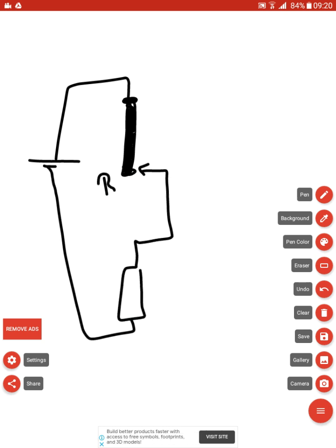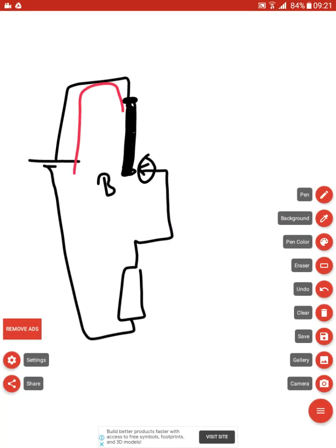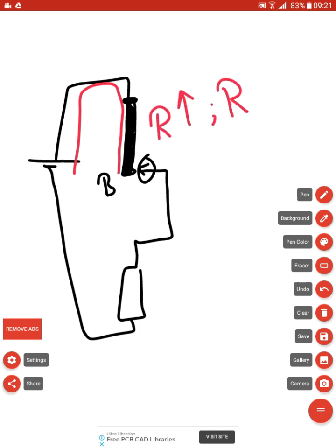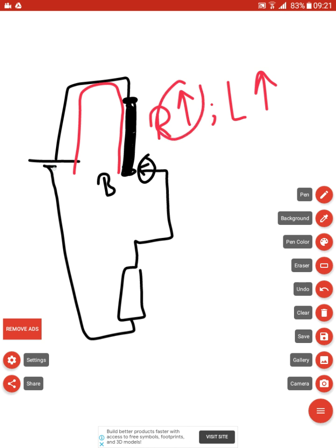If we put the sliding contact at B, the current will pass through a longer path. So we have larger resistance because we have longer length, okay? Higher resistance, so the voltage will split across both of these resistors.